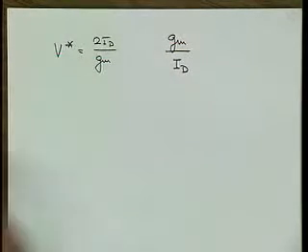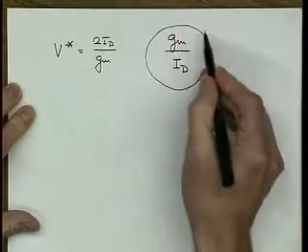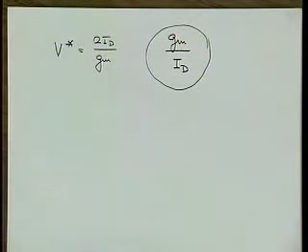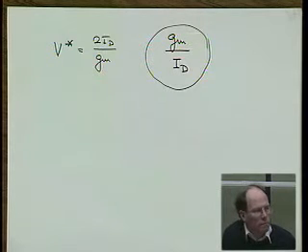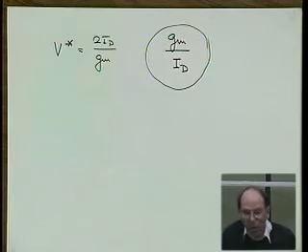Now, really, what we care about is this GM over ID, right? But GM over ID has sort of strange units, and aside from this efficiency in other direct circuits, we much rather use this V star. Now, there is often a confusion about the meaning and status of this V star. And the reason is that for the square law model, V star and VDsat are exactly the same thing. So why don't I call this just V star?